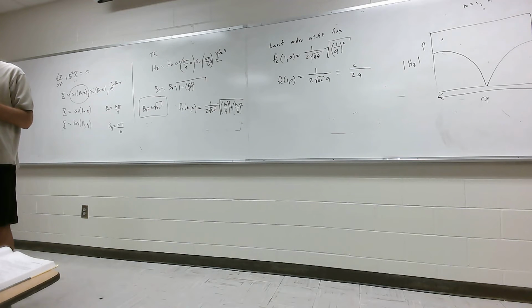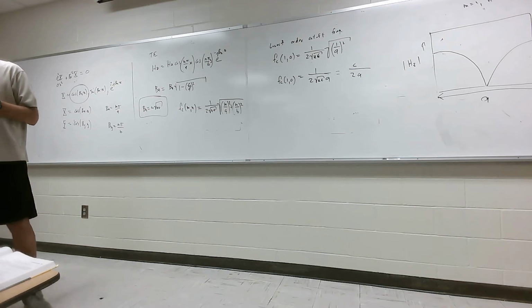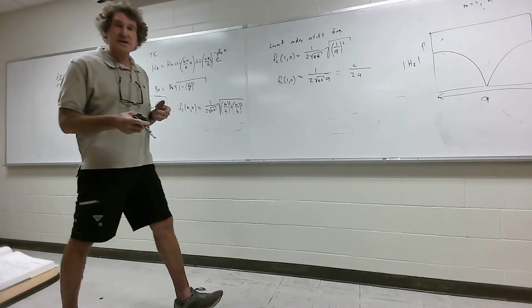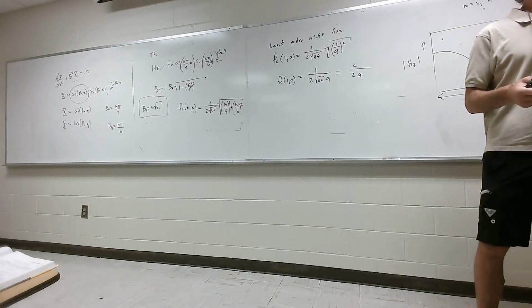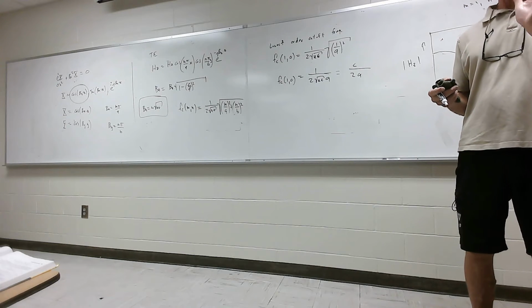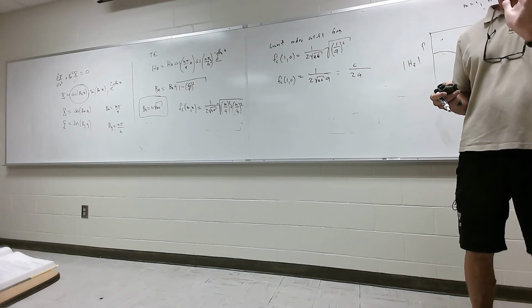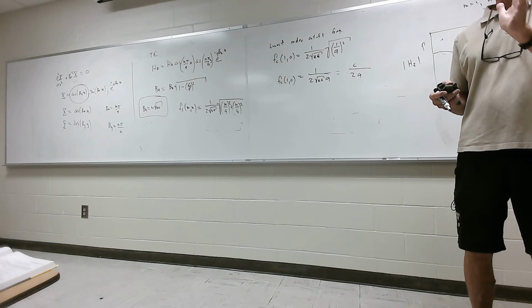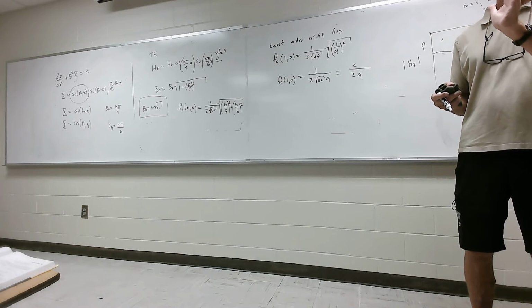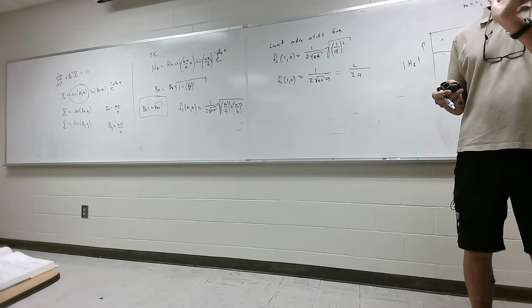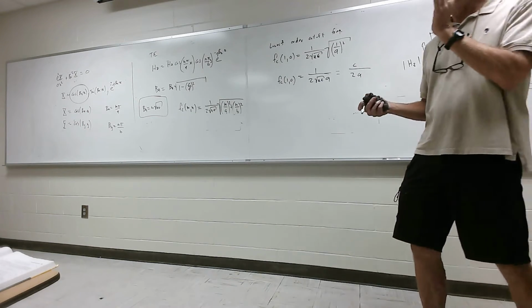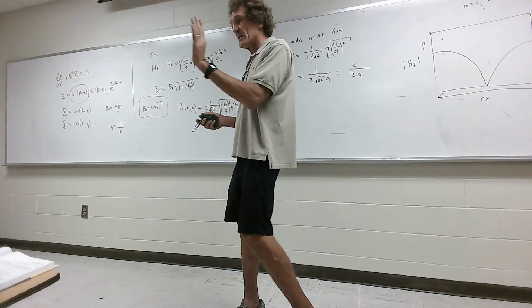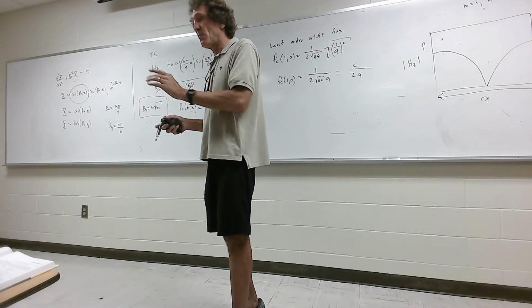Y'all follow me? Normally, if the cutoff frequency is like 6 gigahertz, that would be for an X-band waveguide, then they'll operate it somewhere about 8 to 10 gigahertz, in that range. The next cutoff frequency will be 12 gigahertz. They'll never get near 12, and that will prevent any other mode from ever being developed. So all the electromagnetic energy or power will propagate at the same velocity. Y'all follow me on that? That's real important.